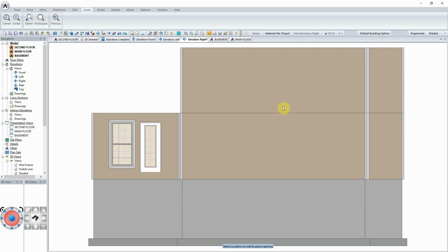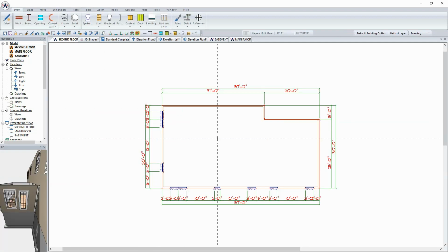structural floor systems, we can now take a look at putting the roofs on. And I'm going to tackle roofs from the perspective that what we want to do is put the roofs on the second floor plan, even if they reference first floor walls. That would allow us to generate a bird's eye perspective all as one drawing rather than having a second floor plan bird's eye and a main floor bird's eye. So I'm going to tackle this from the second floor plan looking down at the first story. And what I'm going to do is change into roof mode here in the upper right hand corner.